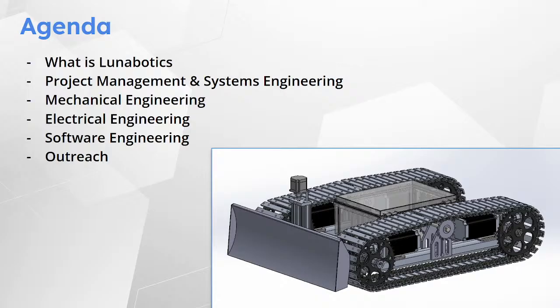Yep, you can see it fits nice and neatly in there. We're still kind of worried about maybe getting to the latches themselves. We can always build some standoffs so that it goes above the top of the track and we don't have any clearance issues. Yeah, they have holes in the bottom. They just kind of have self-tapping screws. It's just going to be a matter of making some L brackets that bolt to the frame and then have holes that screw into the bottom of the box.